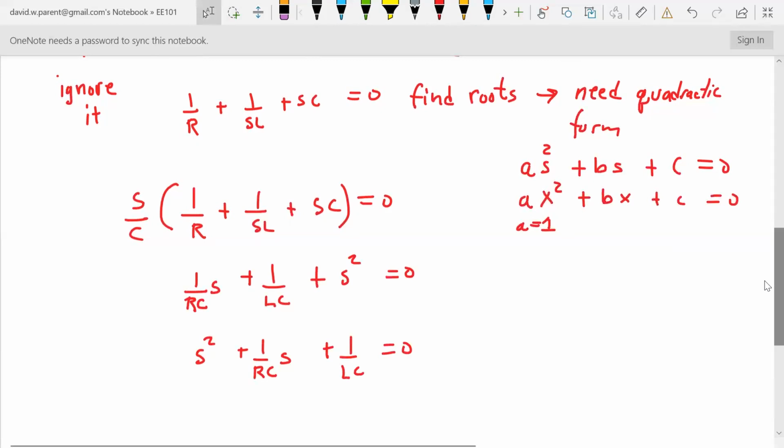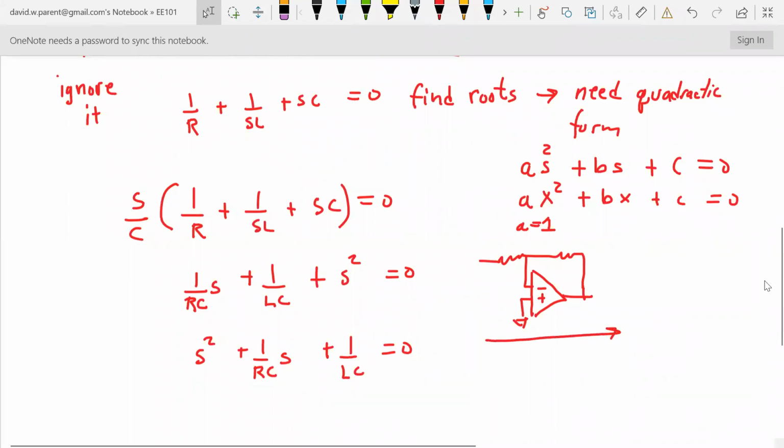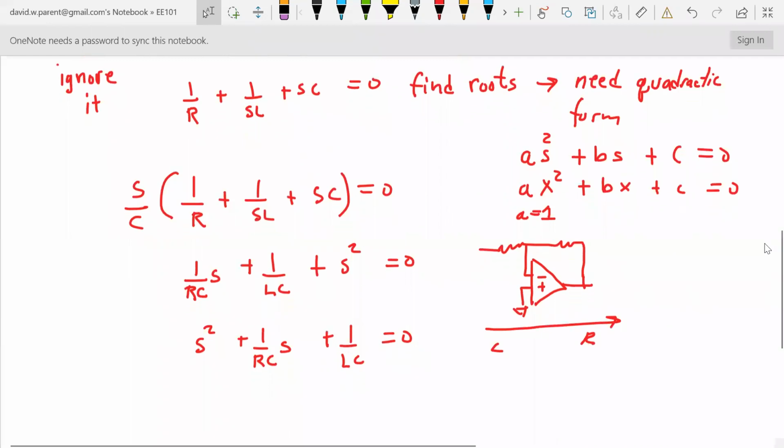Sometimes the way you can think of it is, at work, you'll have standard operating procedures of this is how we do something here, so that you don't spend a lot of time interpreting things. Just as a quick aside, it could be something like whenever we draw op amps, the minus goes here, the plus goes here, and we draw the resistors straight across, so that we all do it the same way and it speeds up communication. Like the signals will always go from left to right. It's not wrong the other way, but it might take more time for somebody to understand what you're talking about.